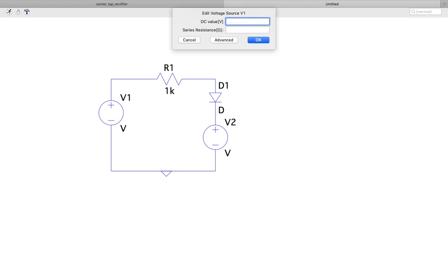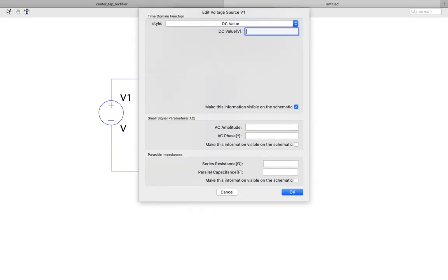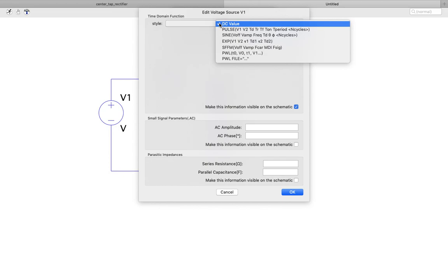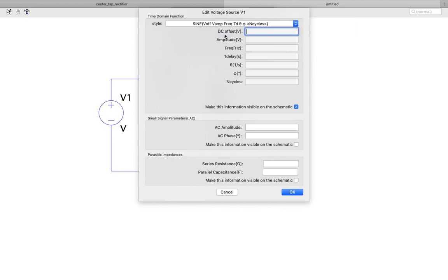of course you need to go to advanced and go for a sine wave generator. So get the sine wave generator. The DC offset will be 0. The amplitude you need to take as 8. This is 16 volt peak to peak, right? So that's why the amplitude will be only 8. You should be very careful. The quantity that you have to plug in here is 8 volt.